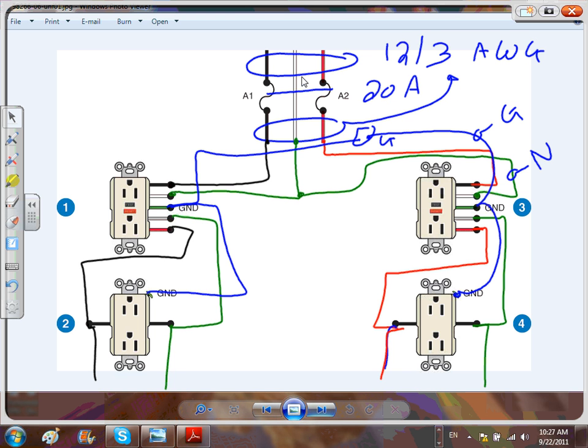If you get into also child care facilities, guys, it has to be tamper resistant. And they define later on the child care facilities as four kids full-time or more, and 7 years or less. So all your grade schools receptacles, right? So you have more than 4 kids, and in grade school and in kindergarten, those are 7 or less, right? So that will make schools tamper resistant receptacles. So anyway, just be aware of that.